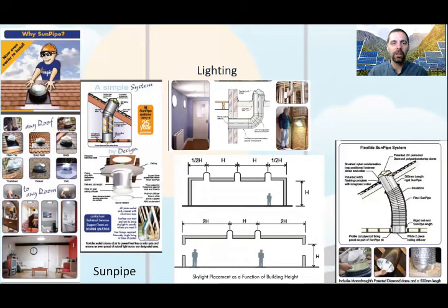On this slide, you can see a popular and useful system. The tubular daylight devices are another type of top lighting device. These systems employ a highly reflective film on the interior of a tube to channel light from a lens at the roof to a lens at the ceiling plane. Tubular daylight devices tend to be much smaller than a typical skylight, yet still deliver sufficient daylight for the purpose of dimming the electric lighting.